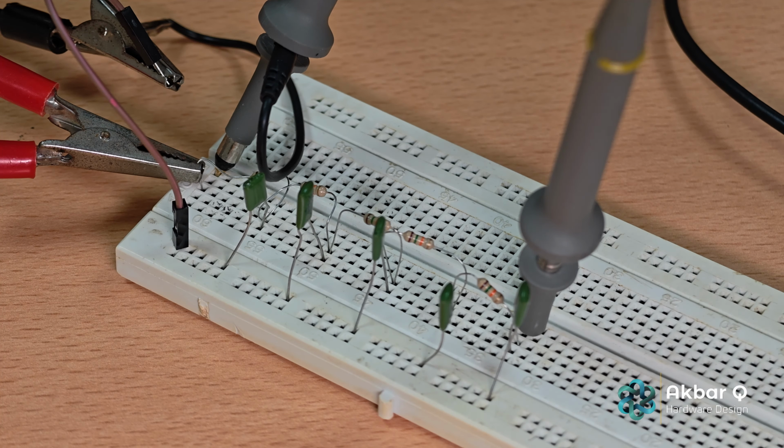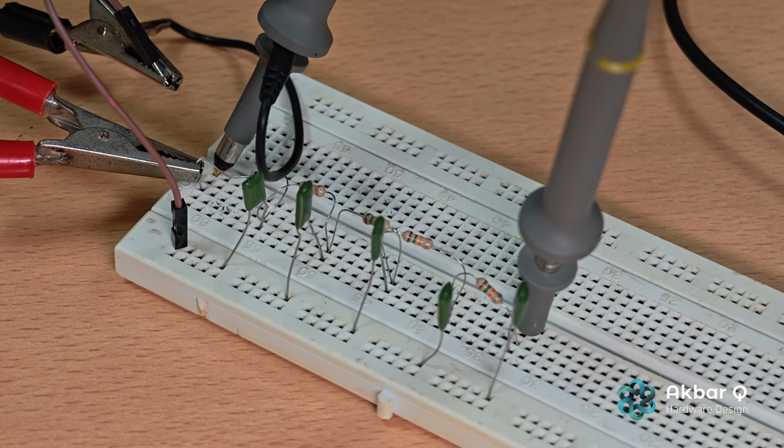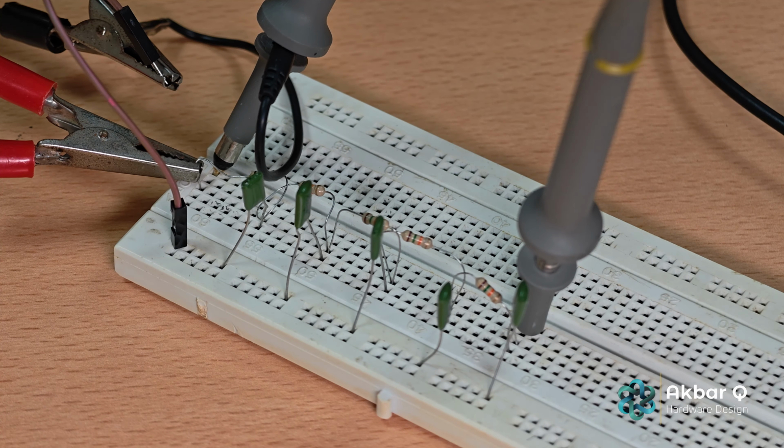Welcome to the demodulation circuit. This circuit is made up of 5 low pass filters. We have a high modulation carrier frequency and then we have a low signal frequency. The purpose of this circuit is to eliminate or reduce as much as possible the carrier frequency. As the carrier frequency is high, we can use a low pass filter, which filters out high frequencies, to remove the carrier signal. The data signal in this case is a low frequency signal. Again, the high frequency signal is the carrier, the low frequency signal is the data.